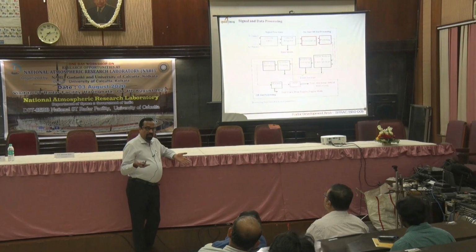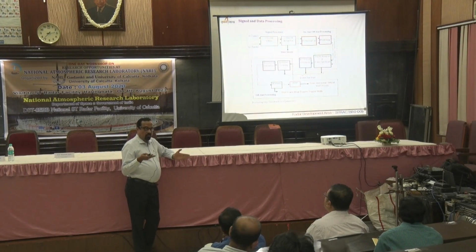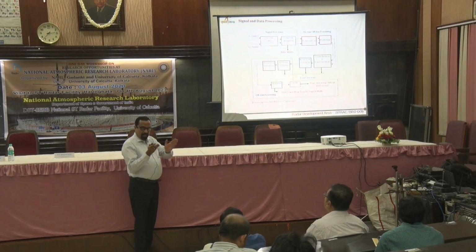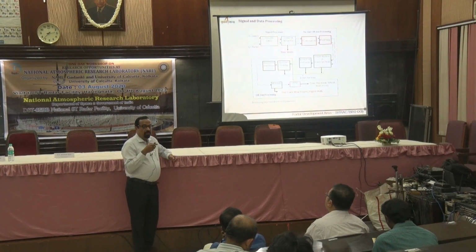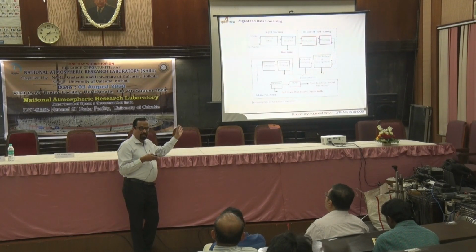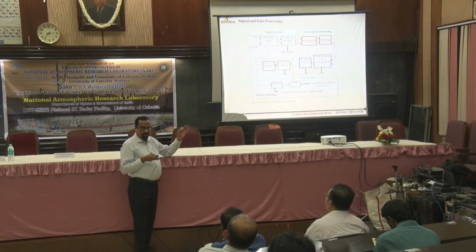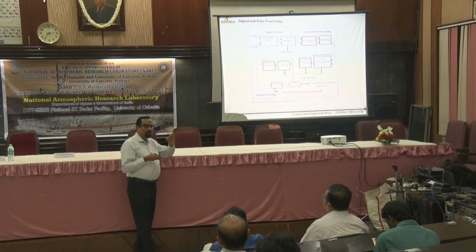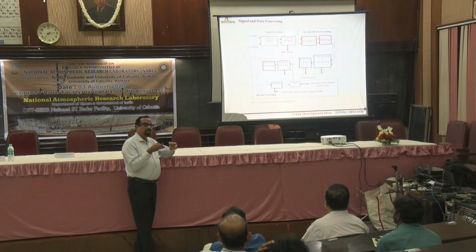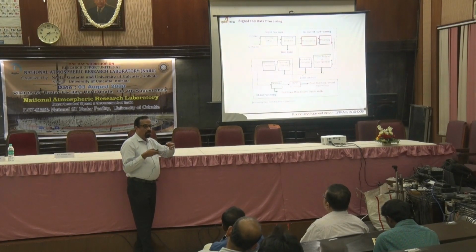Effectively, suppose we have a 1000 Hertz signal, a 1000 Hertz component, and I add it 10 times, it becomes a component of 100 Hertz. But at the same time, if I am using 100 Hertz, I should make sure that my FD, which is the first point I raised, the Doppler shift happening on my carrier signal, should be inside 100 Hertz. That is the point you have to remember. That is the wisdom that has to go in when you are doing an experiment with the radar. What am I doing, what is the impact on my observations, whether it is sufficient or can be used or not, you have to have a judgment. This is very important when you are using radar.